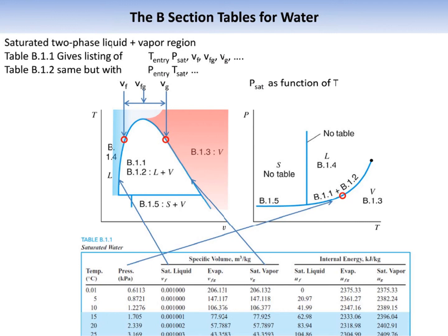Here again we have the TV diagram, and let us correlate how to interpret the volumes that are given in thermodynamic tables in the form of Vf, Vfg, and Vg. So when the boiling starts, when our system reaches this point, a constant boiling temperature may start.